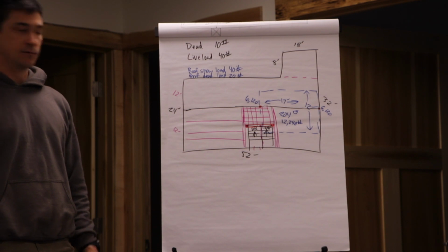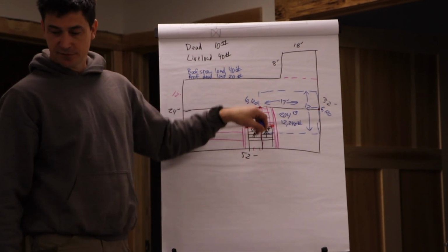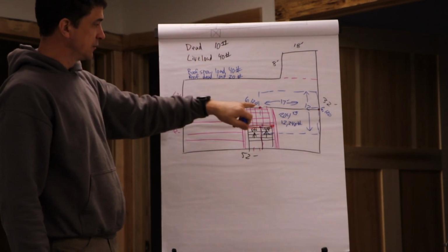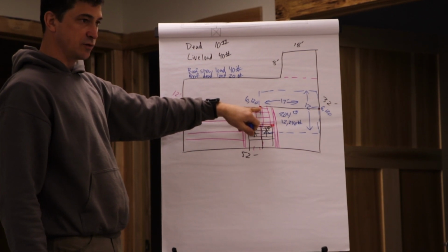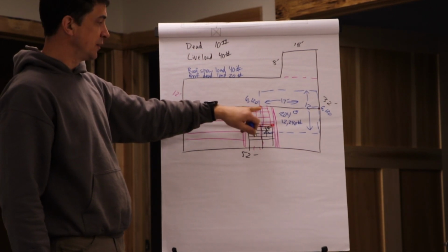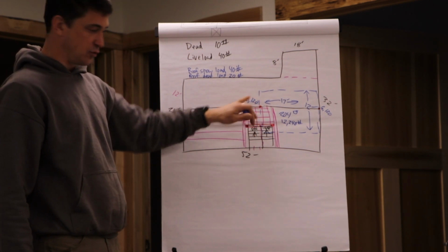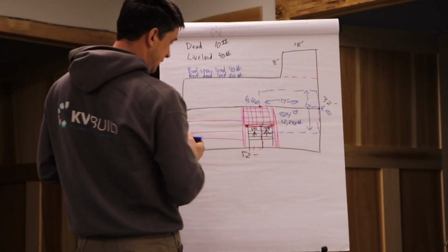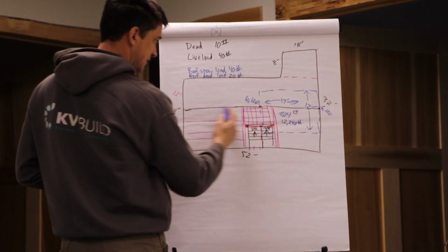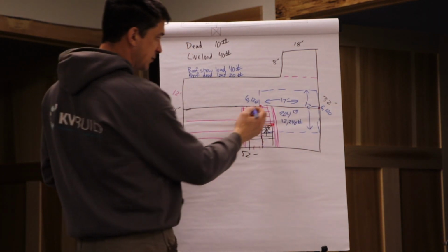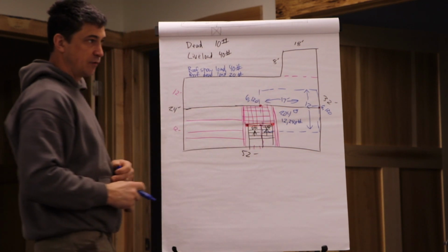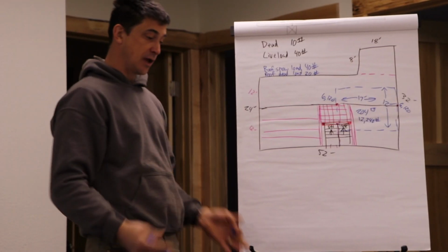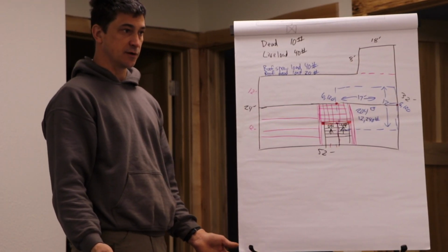That's a relatively light load for a house, but we have to transfer that from the roof down to this first floor. We need to make sure that we've got solid blocking between our floor sheathing and this beam or this wall, and that we've got a post or something under that point going down to the floor. And so when you're framing your basement, let's say this thing's got a full-length wall in there, I need to make sure that I've got something right under that post point that's going to carry a 6,000 pound load. And I may need to make sure that I have a footing under that point in the concrete floor.